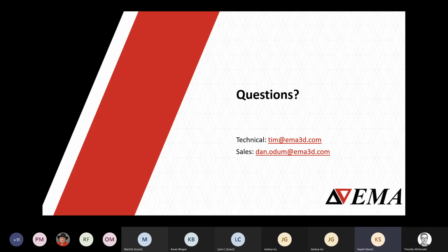Okay, next question. Can we import 3D data for cables directly from the Unigraphics NX? Yes, so NX is a native format that we can pull into SpaceClaim. However, it's not incredibly common that NX defined cables typically are just the outer description of that harness and its path in 3D, which is very important. It is not common that the electrical connectivity, the wiring diagram, is stored in NX.